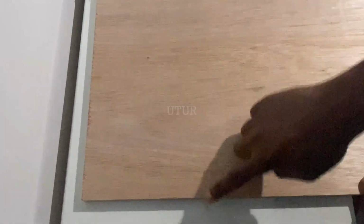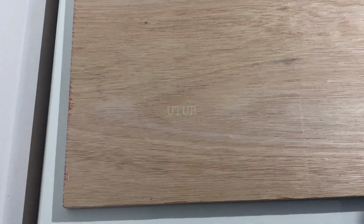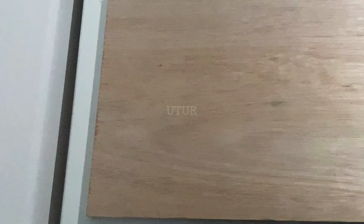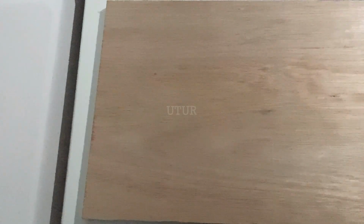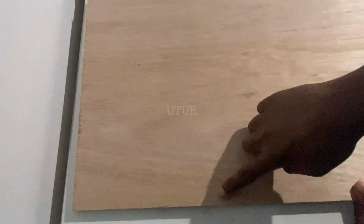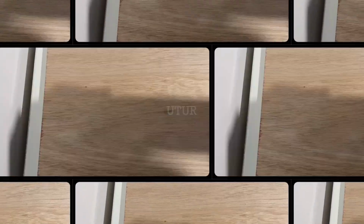An increase in the number of teeth essentially means it will take a bit more time to cut through your plywood, but it does a bit of cutting and a bit of ripping, though not as well as your dedicated cross-cut blades or ripping blades. But you will get better quality cuts with the composite blades. So ideally, a composite blade with a 60 tooth threshold value should be able to get quality cuts off of the plywood. And so now let's move on to some simpler woodworking.